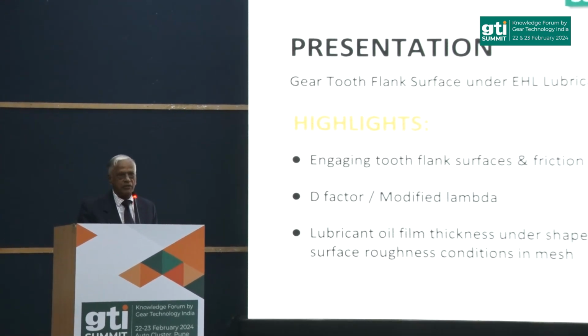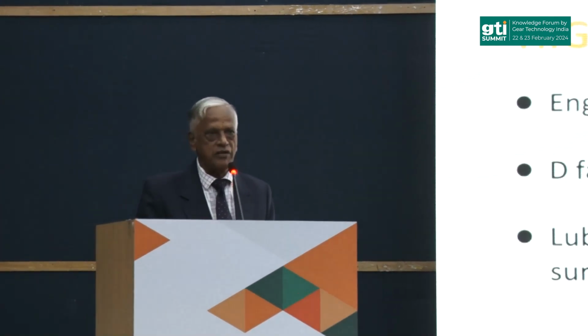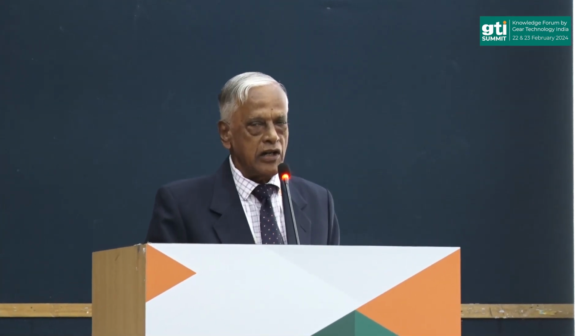In the process, it's not only the load; there is something known as friction because there is metallic contact. To avoid metallic contact, we have lubricant coming into the picture. Let us concentrate on mineral oil with or without extreme pressure additives. What happens to the tooth flanks, or the combination of driving and driven tooth flanks, in the presence of mineral oil, which has some physical and chemical properties, as to how it transmits the load? There's some physics behind that.